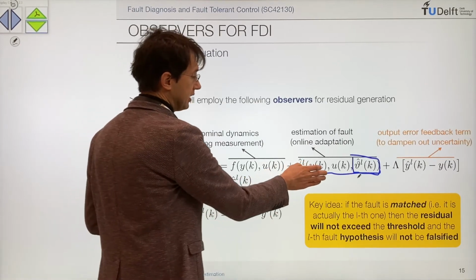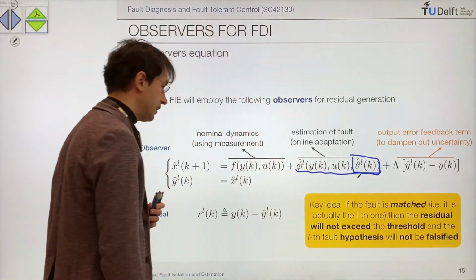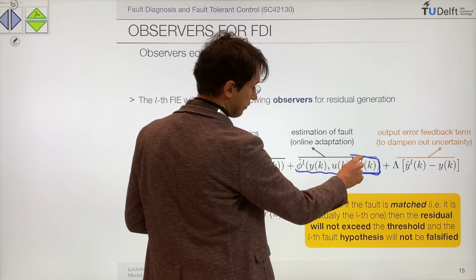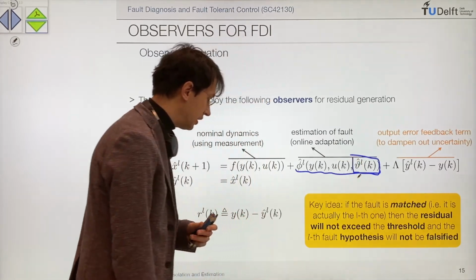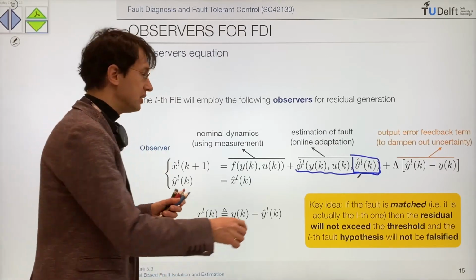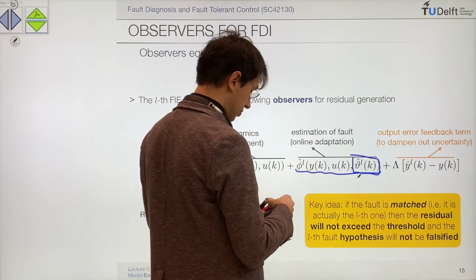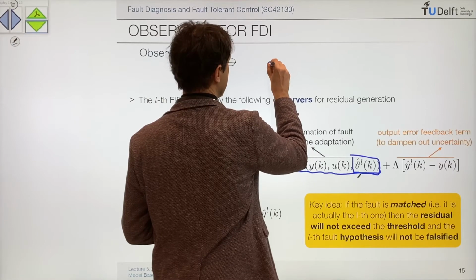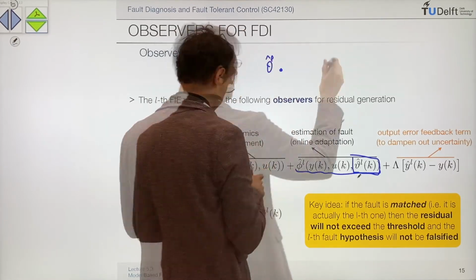So this term basically is our actual belief about the fault at time k. It depends on time k because as we have new data, we are going to update our estimation of this parameter. And hopefully, after we get enough data, this is going to be close to the real one. So we really hope that we start from some value of theta hat L at time 0.